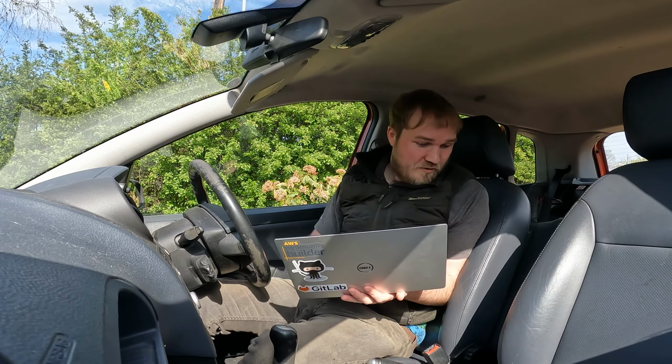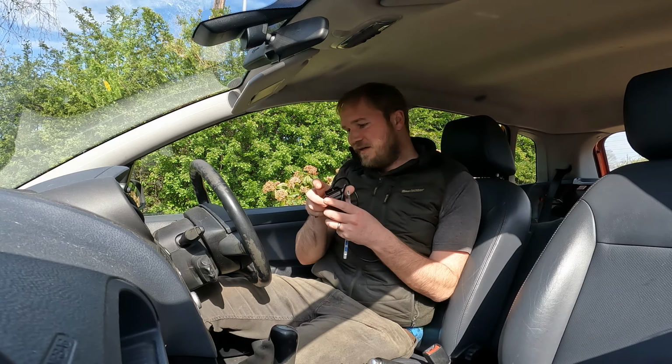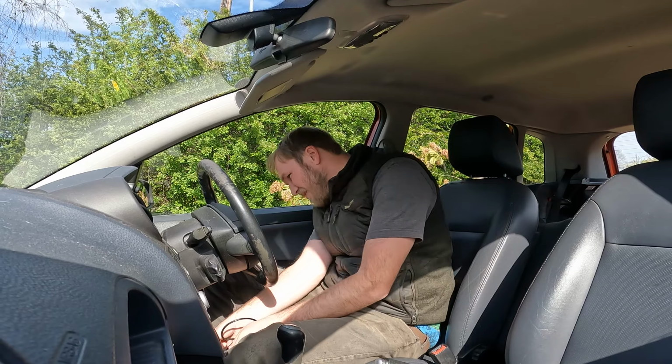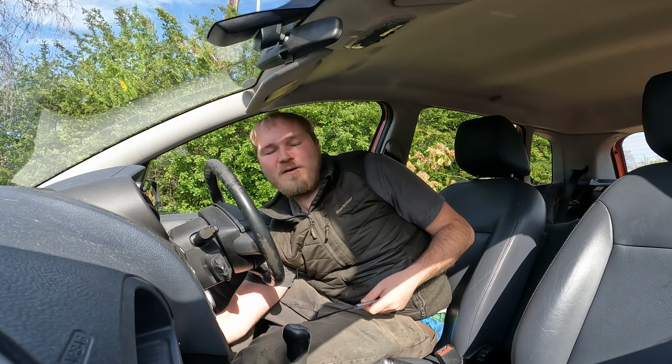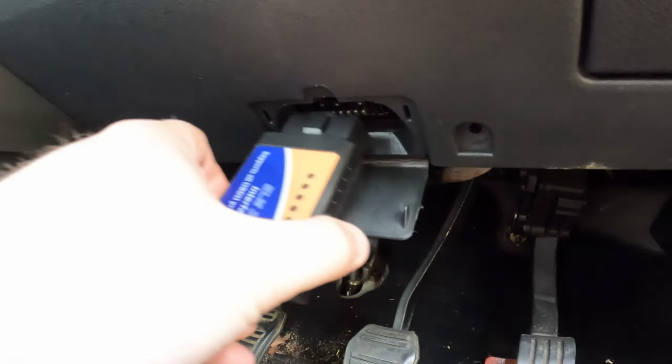Okay, so we've jumped in the car now. So what we're going to do, I've got my laptop, I'm going to grab my OBD2 plug, and this OBD2 plug plugs in the Fiesta. So we're in a Fiesta Mark 6. The OBD2 plug is just under the center column here, and when that plugs in, we should see some lights appear on the OBD2 reader, depending on what reader you're using. I'm going to plug that into my laptop here,